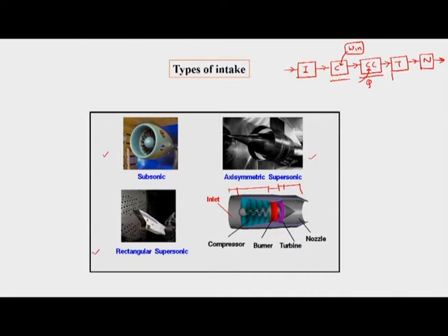So the intake is expected to raise the pressure before the air goes to the compressor. Then the compressor would raise the pressure further, and the pressure rise requirement from the compressor would decrease. This is the major philosophy for having an intake.